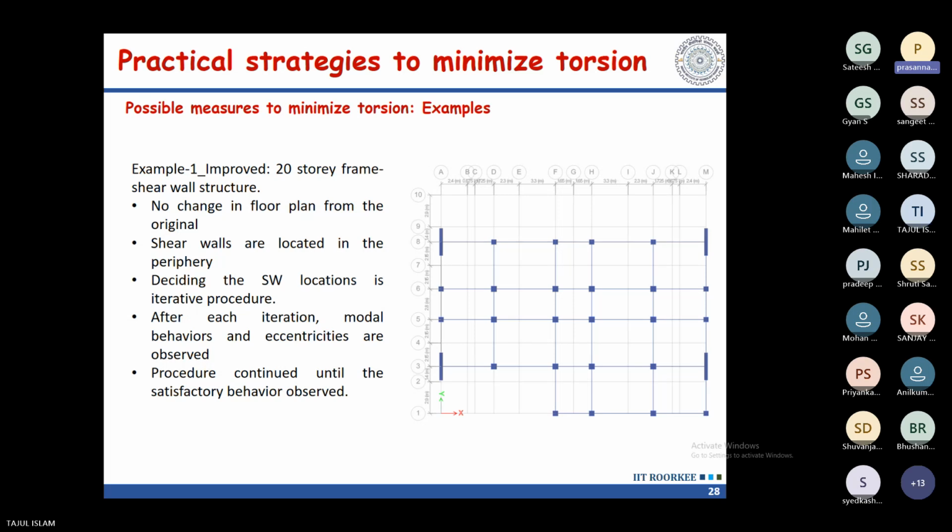Spandrel beam concept. Suppose your beam is 1000 by 600. The same thing can be modeled as a spandrel. That also gives a better torsional resistance. If I model the spandrel beam in the tab, the torsional resistance will improve. But is that the correct approach or not? Because many people will use the spandrel beam.